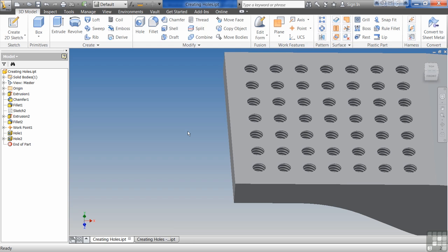Unless you're designing something, if you're designing a screw or you're designing some kind of screw shaft or something like that, where you're actually going to be cutting the threads on a CNC and you need to give the CNC information more than just the thread and pitch. This will actually tell it, okay, this is this size thread and pitch when you put it on a drawing. If you're going to pass this over to a CNC machine and they're actually going to go in there and cut these threads and it's got to realize the 3D geometry, then you can draw them in there.